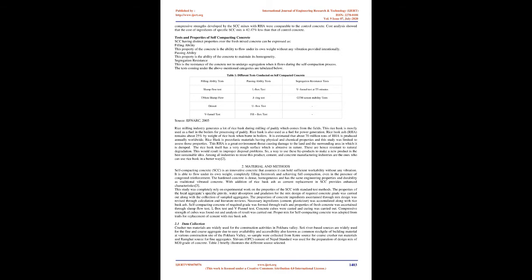Tests and properties of self-compacting concrete. SCC has distinct properties over the fresh mixed concrete, which can be expressed as filling ability. This property of the concrete is the ability to flow under its own weight without any vibration provided intentionally. Passing ability. This property is the ability of the concrete to maintain its homogeneity.